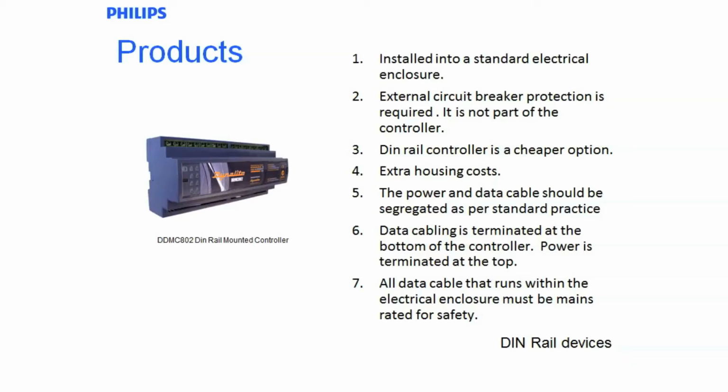All data cable that runs within the electrical enclosure must be mains rated for safety. That means that the installation properties of the cable must be a minimum of 240 volt rating. The orange Dynalite cables that are supplied through Philips Dynalite do have the appropriate installation ratings.